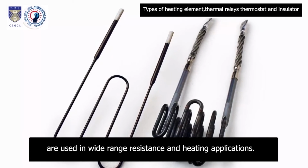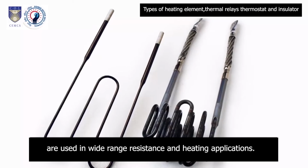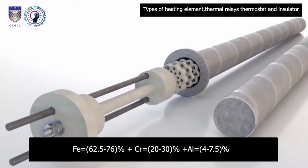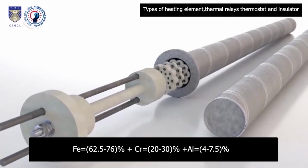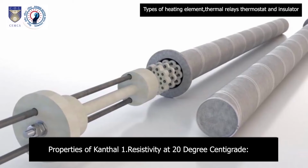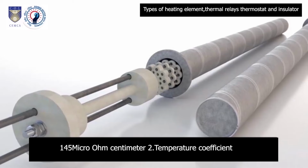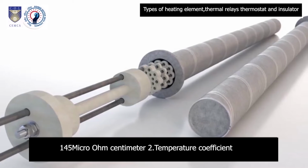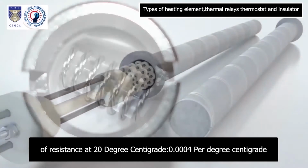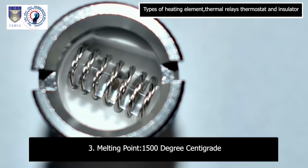These alloys are used in wide range resistance and heating applications. Fe is equal to 62.5 to 76% plus Cr is equal to 20 to 30% plus Al is equal to 4 to 7.5%. Properties of Kanthal. 1. Resistivity at 20 degrees centigrade 145 microohm centimeter. 2. Temperature coefficient of resistance at 20 degrees centigrade 0.004 per degree centigrade.